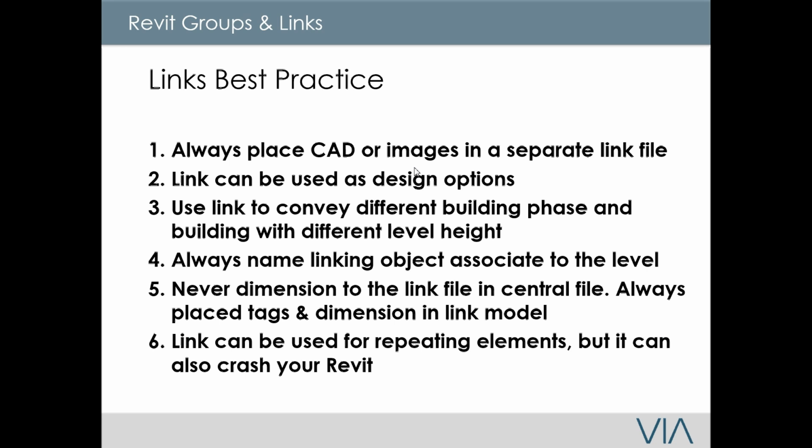If you have different building phases, and it's too complicated and you have a multi-phase kind of thing, you can actually use links to convey different building phases. For example, if I built a school where you have different phases for demolition, temporary facilities, and then the final building, then you could use the links to set it up so that each has its own phase. I won't get too deep into this in this presentation, but the option is there. You can do it. In the future, I'm probably going to demonstrate how you do that.